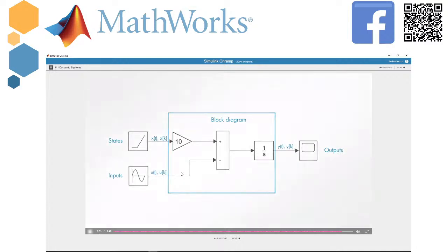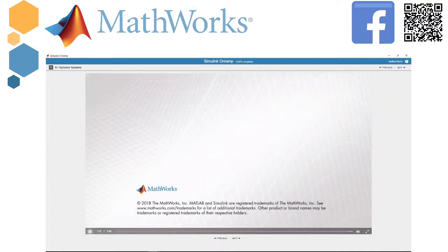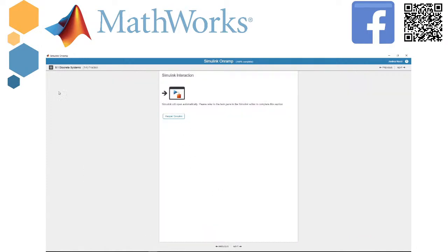So if you want to create the delay, you can just use a unit delay block. So if you have x of k, with a unit delay you get x of k minus 1, and you can just work on it. For instance, here we have this example. Arrange the equation so that the most delayed state is on the left hand side.